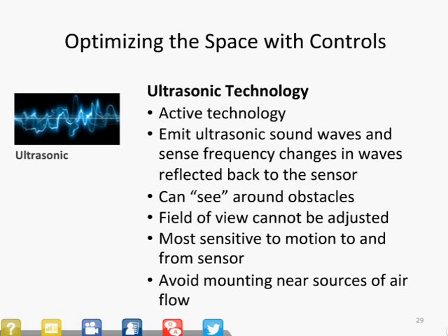Ultrasonic sensors can see around obstacles and are more sensitive than PIR, but they can't adjust the field of view. And unlike PIR sensors, ultrasonic sensors are most sensitive to people walking directly towards or away from them as opposed to across. One thing to note about this, too, is you should avoid mounting these near airflow. They should not be mounted anywhere within 6 to 8 feet of an air source, nor on a surface where there's excessive vibration. And that's going to be important in a data center as well.